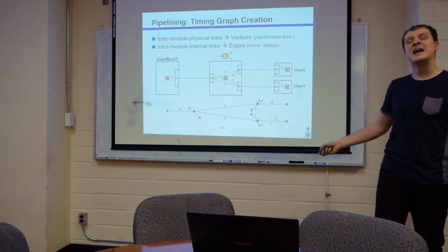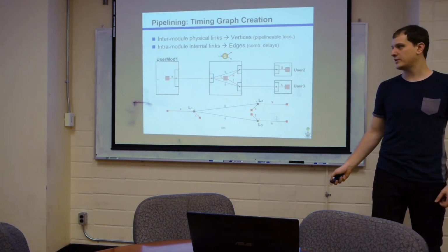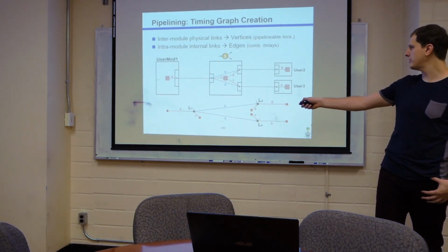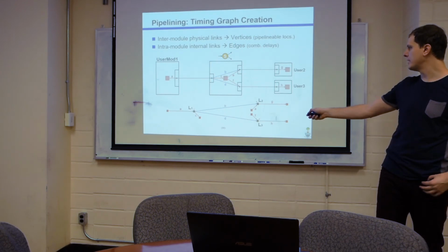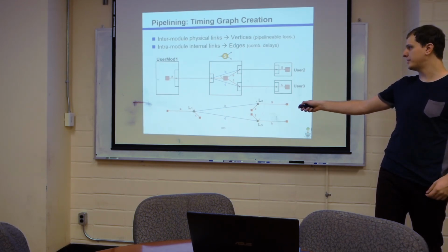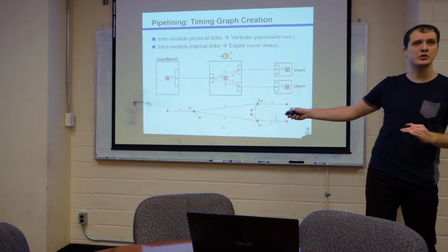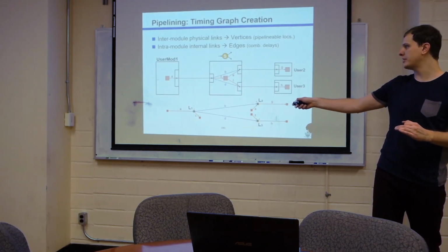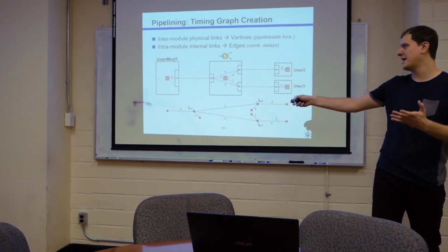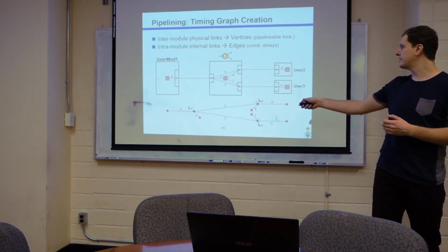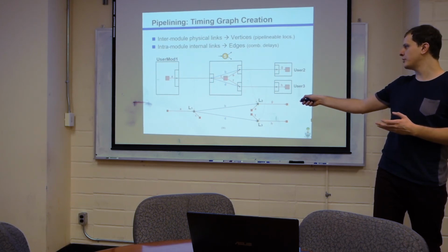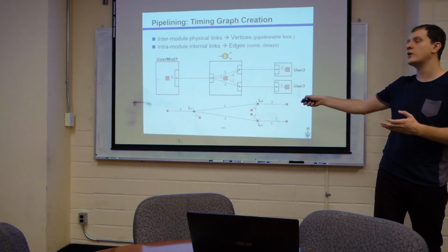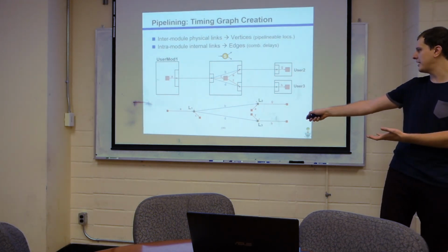Edges in the timing graph get annotated with logic depths, and you can see where they come from with the letters and where they end up over here. There's 2 sources of logic depths. There's ones that originate from or terminate at these internal registers. For example, for this user module, there's some logic depth A that exists between the register inside and the port, or inside the split node here where there's an internal register and it's related to all 3 ports. There's connections between all of them and they all have their own logic depths. Those get annotated at the bottom.